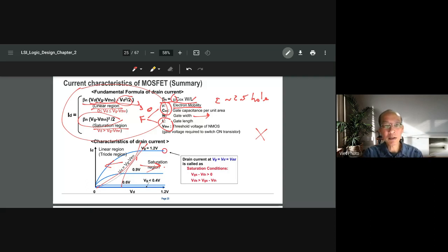So remember from here, again, what we need to do to increase the current is increase the width. And because of the mobility, when the cell designers design, they will have to make the P transistor bigger than the N transistor so that the CMOS has a balanced outcome, balanced voltage or balanced current actually.